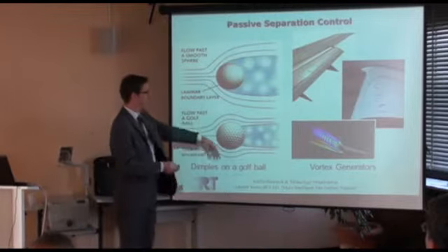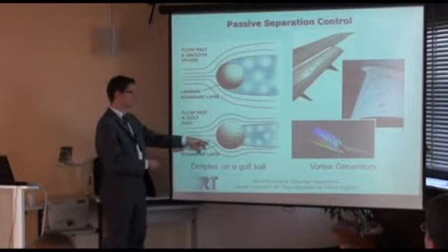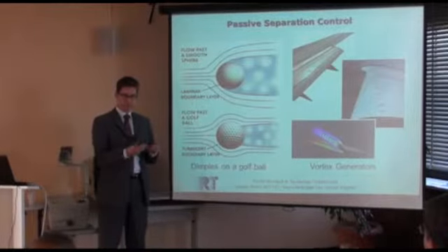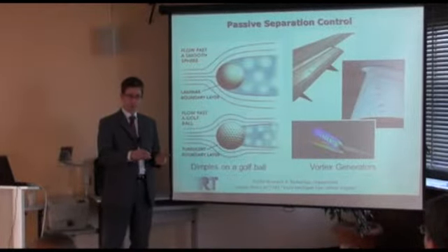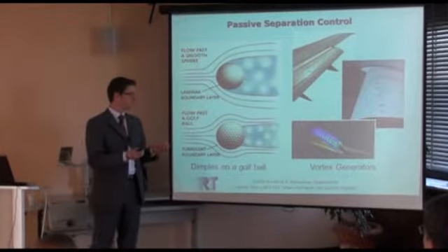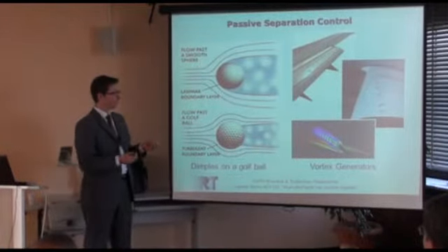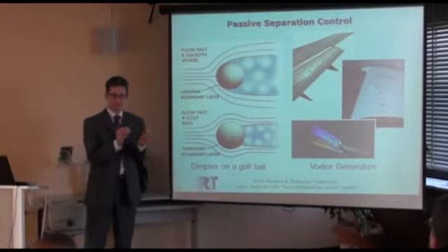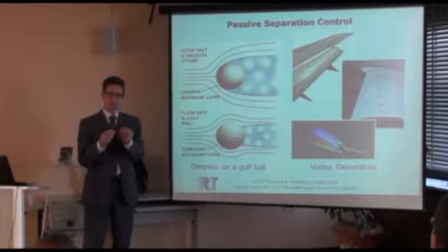It's this part here. So what you do is you turn the state of the boundary layer from laminar flow to a turbulent one. Turbulent means that there's a flow not only going in one direction, but going in different directions, three-dimensionally.